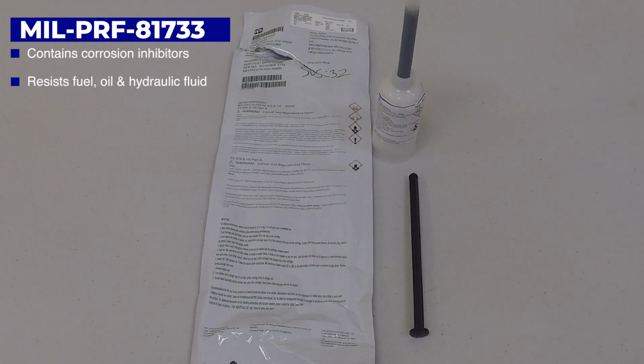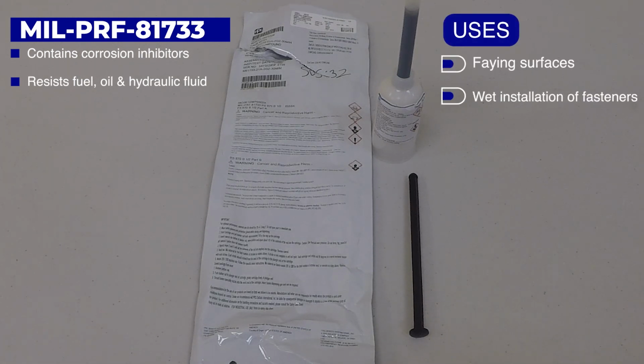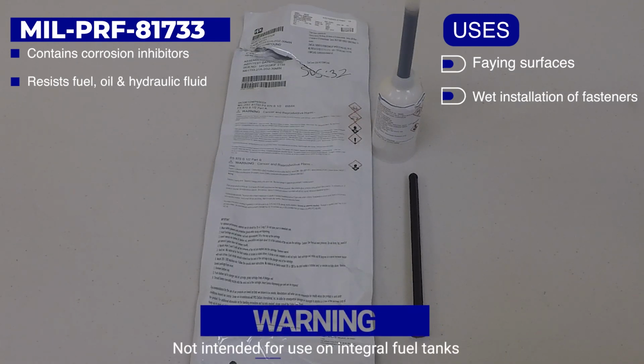MIL-PRF-81733 sealant contains corrosion inhibitors while resisting fuel, oil, and hydraulic fluid. Seals faying surfaces and is used for wet installation of fasteners on permanent structures. Not intended for use as an integral fuel tank sealant.